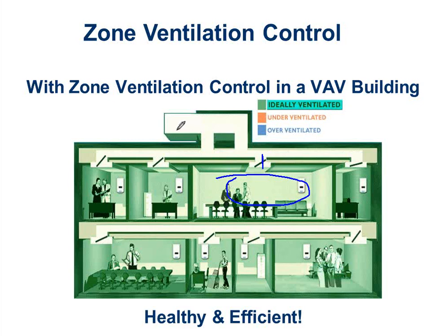At this point in time, I still have done nothing with my outside air damper. He's still fixed. I'm just opening up my zone damper more and getting any more fresh air I can out of the existing duct system. And as he's opening, chances are these other zones might be shutting. They might not be, depending on who's still in those rooms.